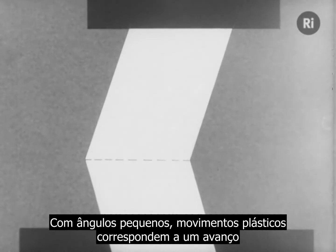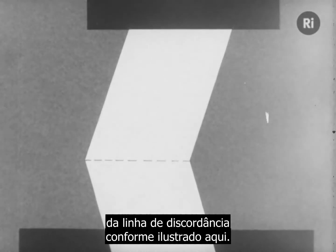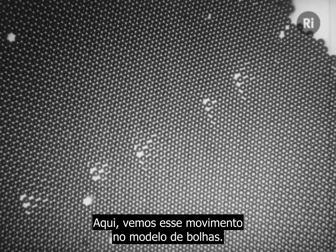With small angles, a plastic movement corresponds to an advance of the line of dislocations, as illustrated here. Here we see this movement in the bubble model.